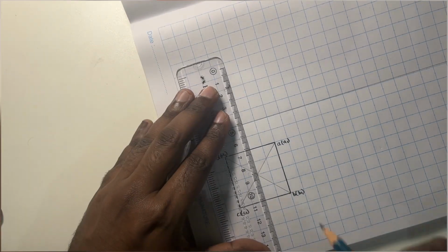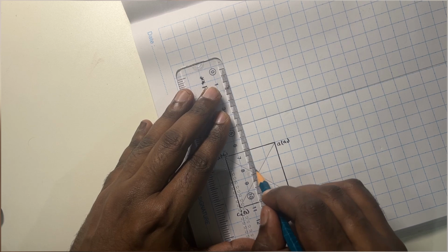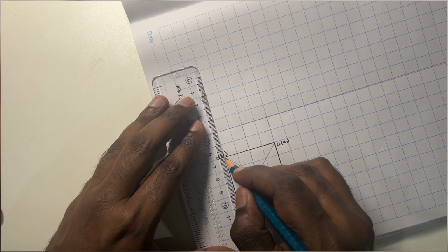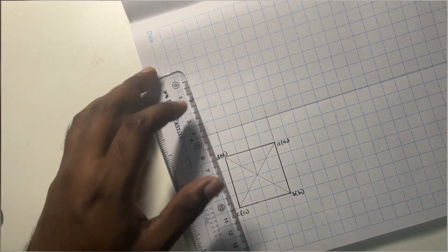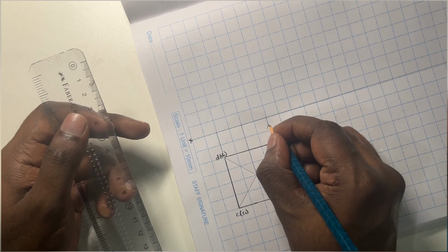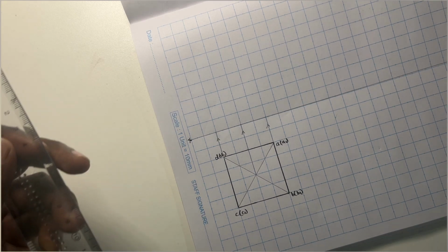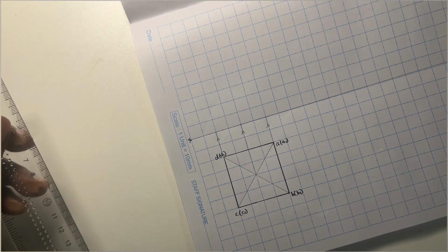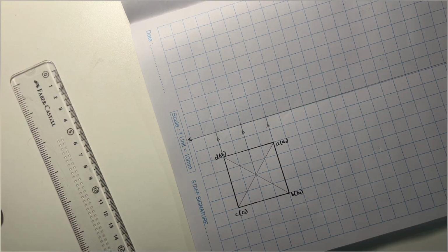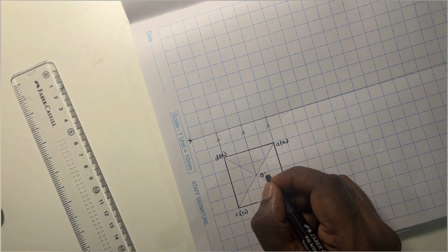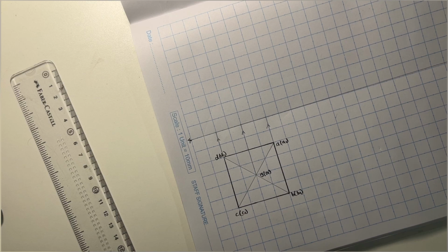So from here, let me draw the projection lines in order to complete the front view of this cube. From each of the corners, I'm drawing the projection lines. Let me just indicate the directions of these projection lines, and also annotate the axis. So O is the axis on the top face of the cube and O1 is the axis on the bottom face of the cube.